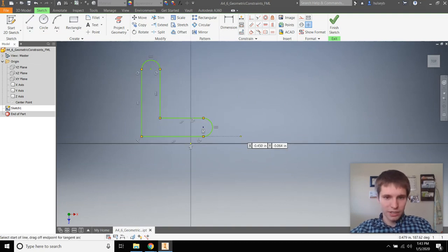Now I kind of want a T that's going up this way, and I want those to have these goofy looking arcs coming from here because I want to do a concentric constraint on those, but let's make them goofy right now. Okay, so concentric means same center. I want that line and that curve and that curve to have the same center. There we go. And it did a weird thing here. That's because I can just move this line up. It has a lot of freedom.